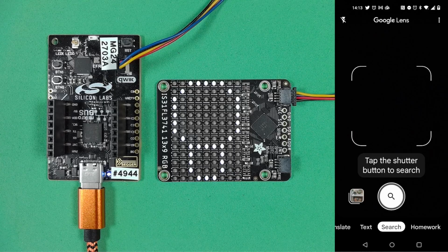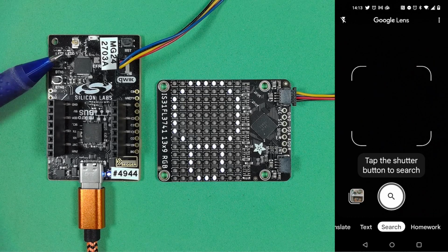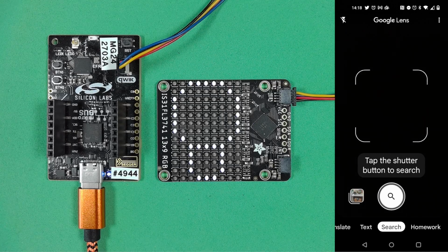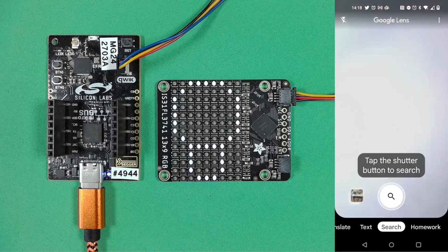The device indicates that it's looking for a network to join by briefly flashing LED 0. This indicates that it is advertising on Bluetooth looking to set up a network. When my phone connects to the device to exchange the thread network information, it will flash more rapidly, and then it will come on solidly once the device is fully in the network. So I'm now ready to scan the QR code and begin commissioning the device.